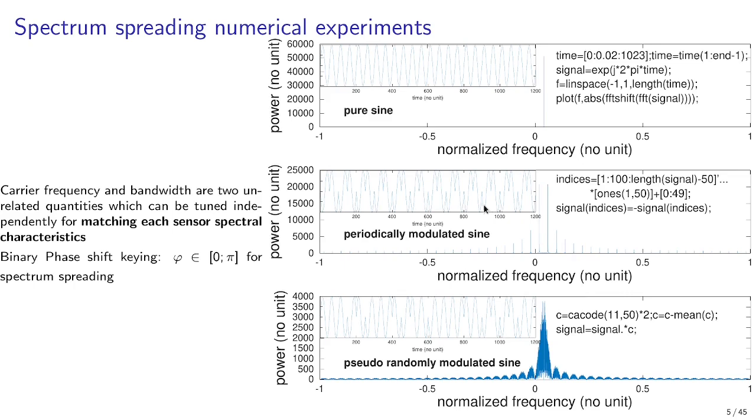periods can be detected. If we generalize the concept by using a pseudo-random sequence, or a non-repeating sequence of phase flipping, then only when this sequence of phases is detected on the ground will the correlation detect the time of flight.